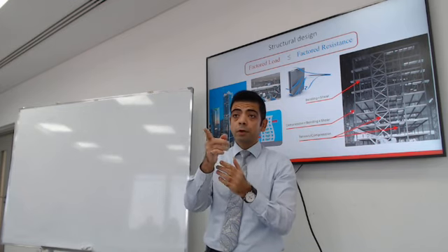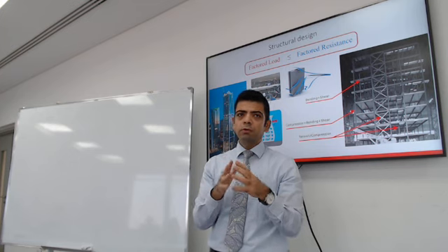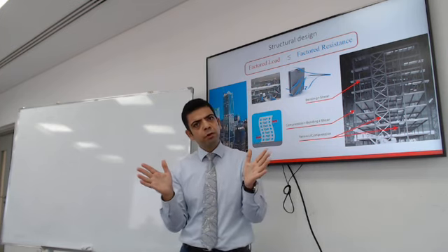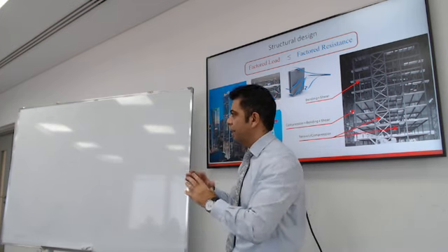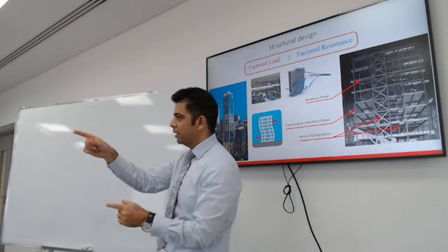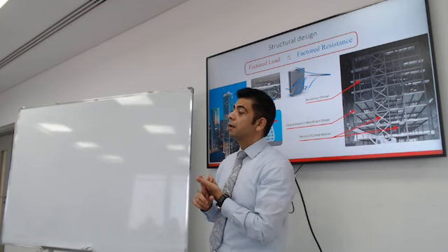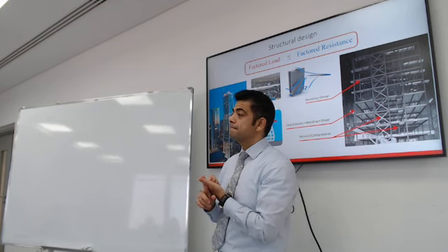Now you know the load, you calculate the bending moment and shear force and reactions. What do you do next? Is that you're done with the design, you figure out the load, and you design the beam? Calculate the shears and bending moment. Calculate shear and bending moment. Perfect. Then using the unfactored load, we figure the deflection.